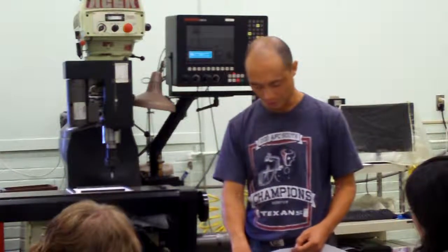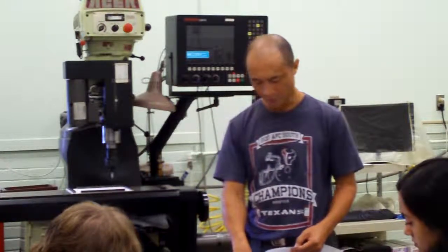Then after this was done, at M40 we come back to G0. We used to be in G1, now I changed to G0 because with this motion we're trying to lift up the pen. We don't really do any work. So just quickly lift up the pen to a height of 0.2 inches above the surface. Then while the tool is above the surface, we move it to X1.5, Y1.5.